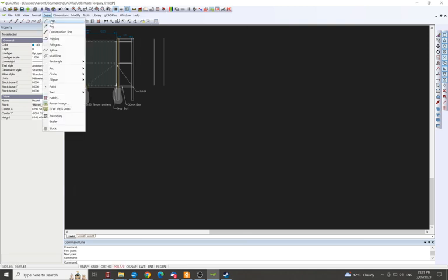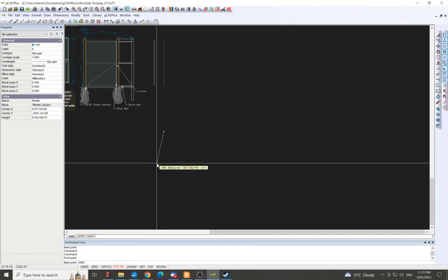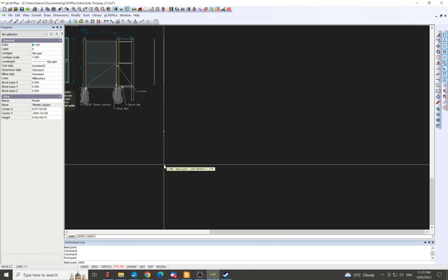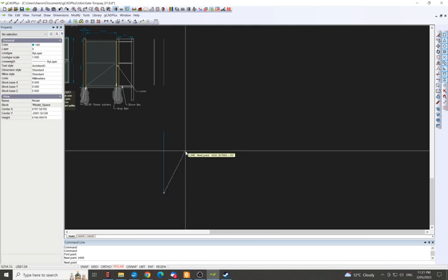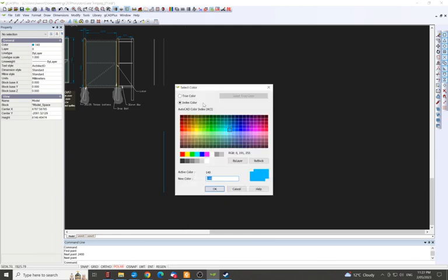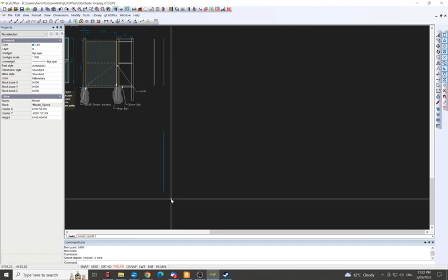Okay, draw line, post to 2400, so it's snapping down to 270 degrees. And we just type in 2400 into the command line and make sure that's sitting on the polar snap. Just press enter. I got 2400. It's in blue, the colors. That's why I have it selected. I had it selected because I was doing some tracing, and I'll do another video on that another time.